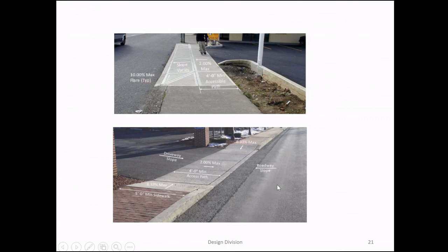So be careful when you depress the driveway if the property is lower than the street. By lowering it, you're going to push the water to the property, so just be careful with that. In that photo on the top, you've got to be careful too. You're probably going to be looking at sections where those curves, you're probably going to have to reconstruct that too.